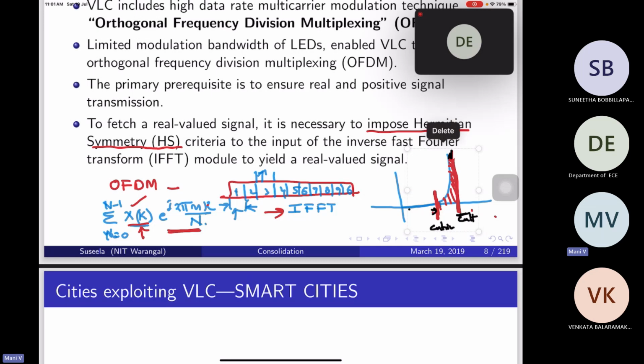So the diode can operate only in a limited region. If it goes beyond that region, it goes into saturation. But we are transmitting some kilobits per second using orthogonal frequency division multiplexing, right? So many variants of sinusoidal signals we are transmitting. Can that amount of current be accommodated in a small region between cut-in and cut-off? It is not possible.